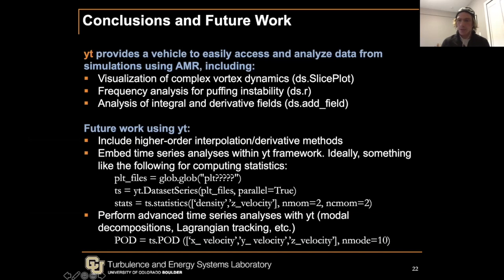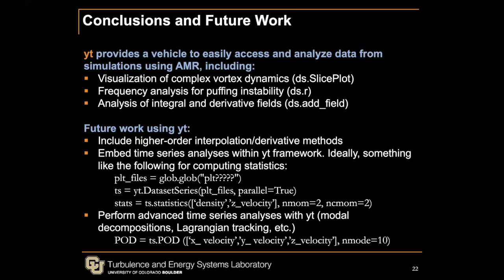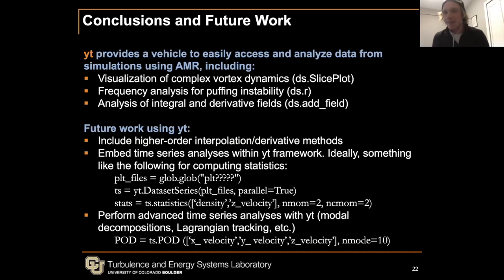POD basically forms a set of basis functions that are optimal in capturing energy, or I guess you would call it variance, of the flow. Then you can use these to build reduced order models or just understand more fundamentally what's going on in the flow. If that kind of makes sense. It's a little bit easier if I had a slide showing it, but I don't have one prepared. Sorry. No, that's interesting.